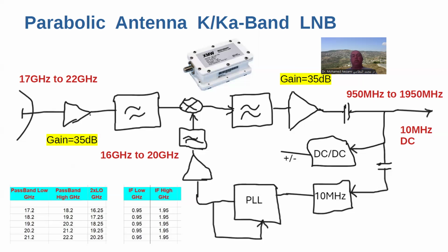The phase lock loop is a chip from TI or Analog Devices. We're going to pick that up. And of course, there's MMIC and ceramic filters, a MMIC amplifier and ceramic filter that cleans out and level shifts the carrier out of the PLL. Now the rest of the stuff is basically regulators, DC to DC regulators.